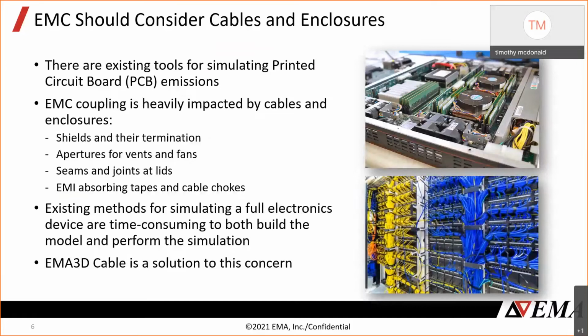Now, enclosures and cables are complicated. So we've had for a long time a collection of really great tools for simulating PCB emissions and other criteria with respect to EMI/EMC. But as you know, that cable coupling is heavily impacted by the cables and the enclosure. For radiated emissions in particular, shields or lack thereof, and the termination of those shields, whether it's a pigtail versus a 360 termination, whether the shield is grounded on both sides, those have big impacts on the emissions.